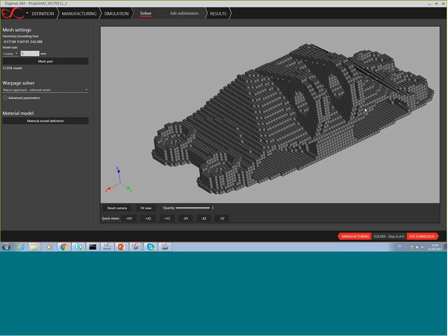But then if you want to relate this to material behavior and understand, does it affect the stiffness or the strength of my material? This is indeed happening inside MF and FE. So Digimat MF and FE are the modules to do material engineering, so characterization of the material properties as a function of the constituents and the microstructure. If you know the microstructure that is set by your manufacturing process, Digimat MF and FE can tell you what material properties result from this microstructure.